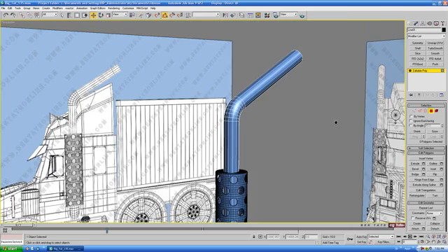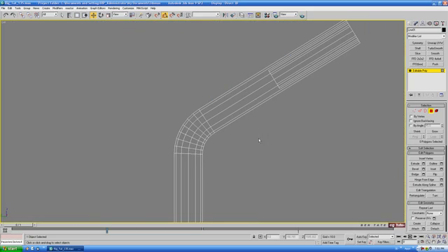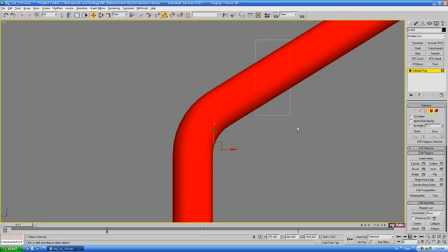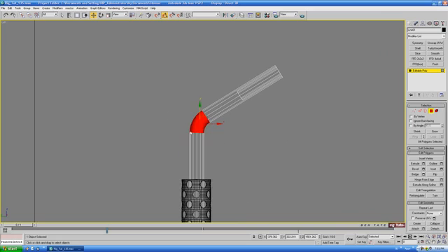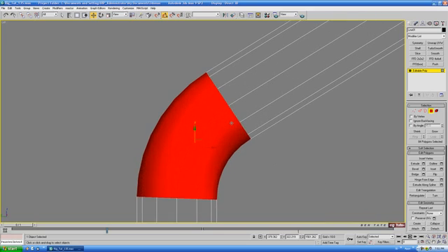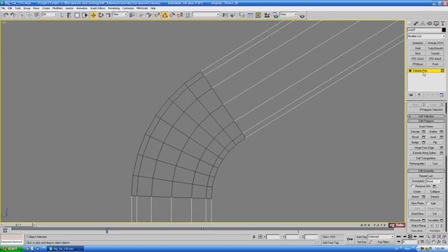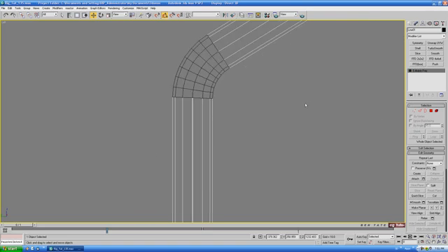Okay, and let's also maybe go back to the left view here. Let's select these polygons here. Let's deselect these ones and these ones. So we have the corner ones that are selected. And let's go over to detach, and we'll uncheck detach as clone. Alright, so this will make it a separate object. Hit OK to that. Okay, that'll break those off.